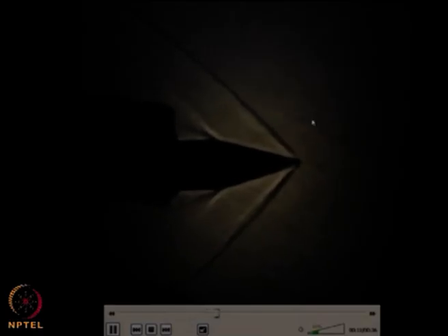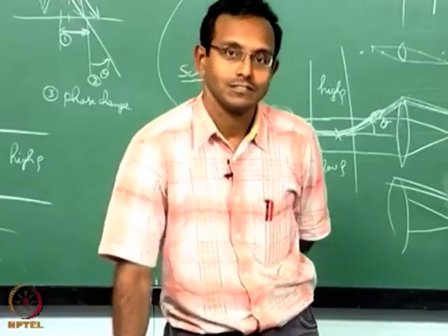Here you can also see the expansion fan and also the Mach waves. You are seeing thin lines coming in from these sides. The way we got the thin lines here and here is by putting thin grooves on the nozzle. So we used that to form these thin lines. We'll look at more next class.